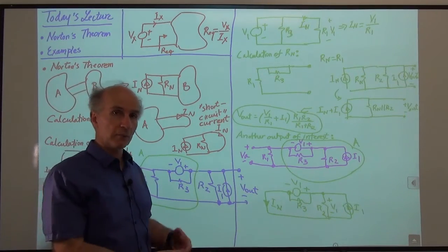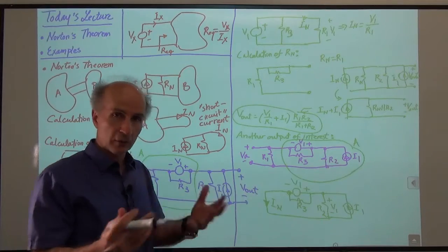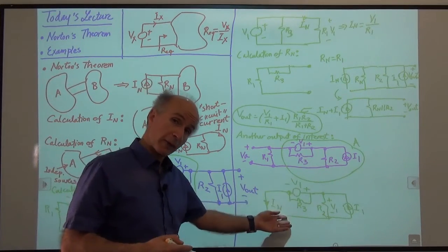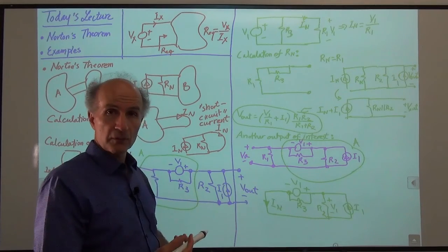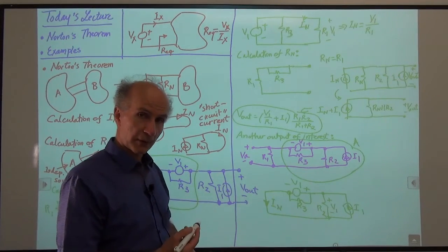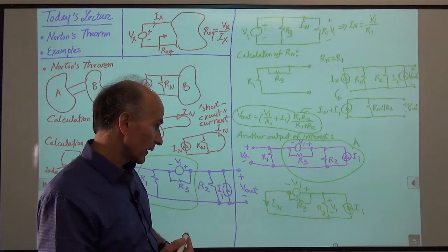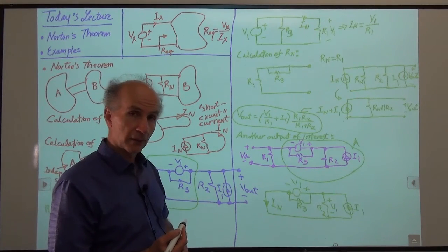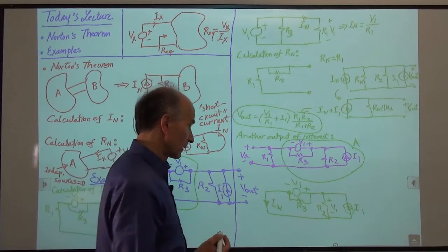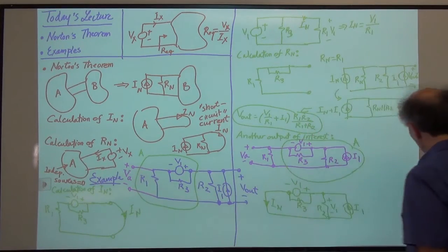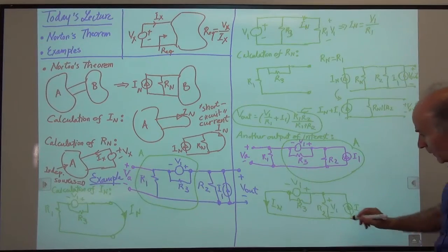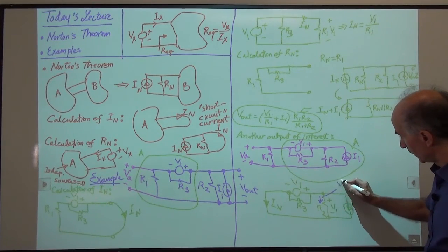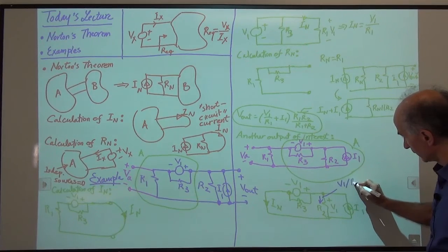All right, so I'm solving the circuit by inspection. You can always write your nodal equations and so on. You can always try to apply Thevenin and Norton to this one as well, right? But we can try to see if just by inspection we can solve the circuit. Okay, so then because I have the voltage across R2, I have the current through R2, right? So this current here is given by V1 over R2.